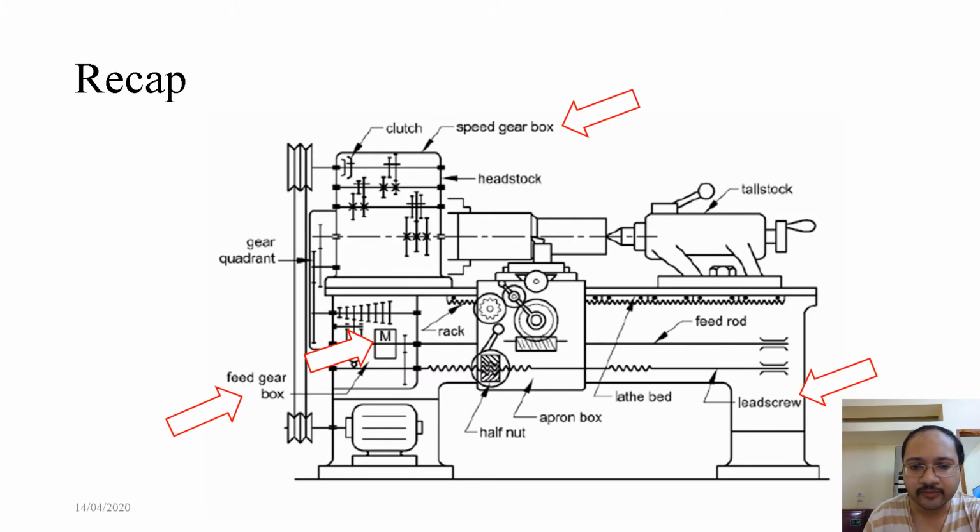In the figure, we see meander drive is represented by M, which helps to meander or direct the power from the motor through a lead screw to provide the feed motion. The word meander suggests that the power of the motor is not directly fed to the feed motion. Next, a thread is cut on a lathe with the help of a meander drive, the lead screw, and carefully engaging the half nut for auto feed. Different variants of pitch can be cut, which we will discuss in module 9C.